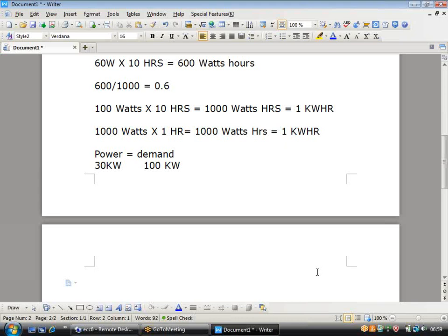Either you can use a separate meter called a power meter, or you can also use an energy meter separately, or some meters are coupled with both. They have the capability to record the instantaneous power demands for a period of 15 minutes and also the regular aggregated, cumulative data for the energy consumption. But the energy meters are all aggregated. They will keep on measuring and aggregate, and then you see. But power meters are not like that.